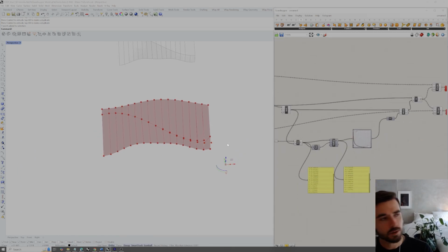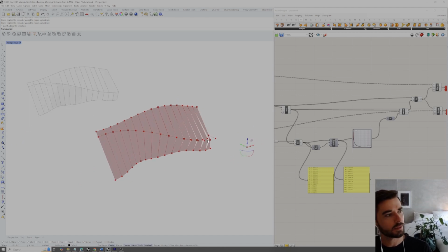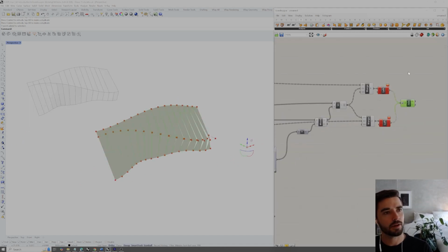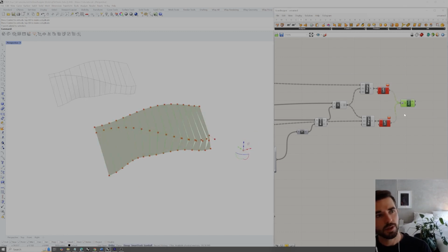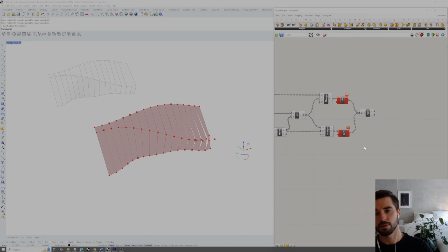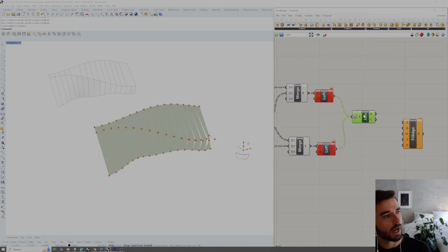Okay, and now once you've done that, we've applied the actual openings. The next step is, instead of just immediately joining these, we want to join them and then perform some smoothing operation. And just like in the first Rhino video, what we actually want to do is apply a fillet edge. And that's going to be this kind of volumetric looking one, so fillet edge, which will apply to surfaces or B-reps. We're going to take the output of this join set of B-reps,